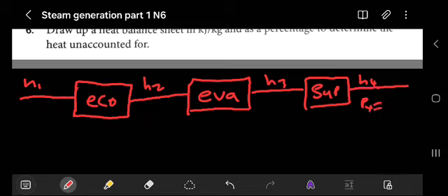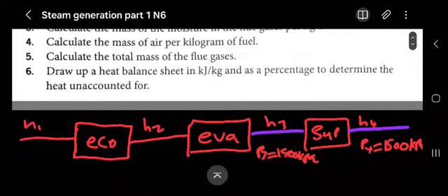The pressure there, which is the same as 1500 kilopascal. Remember, the pressure here and there is the same, so P3 is equal to P4. That means the pressure here at P3 will be equal to 1500 kilopascal also. And this is what we know. Remember, those are superheated.